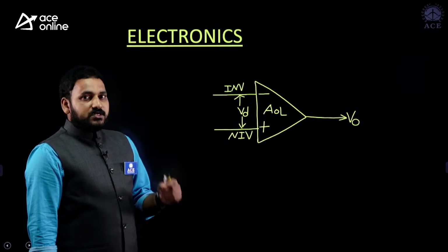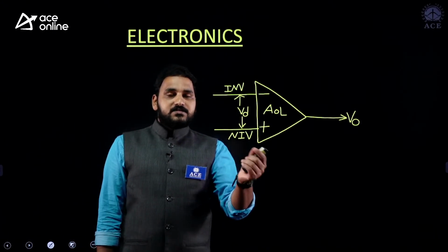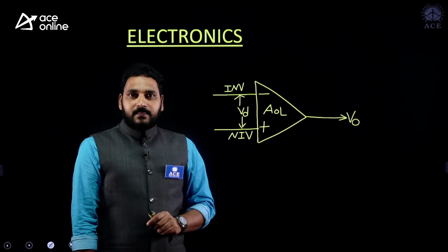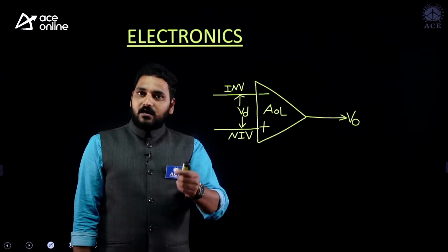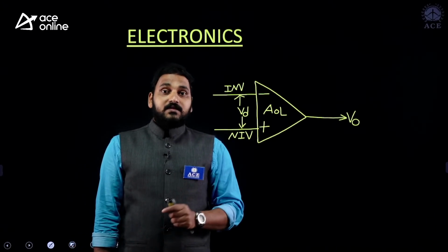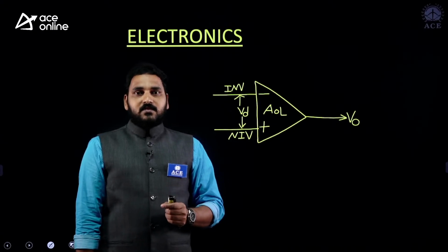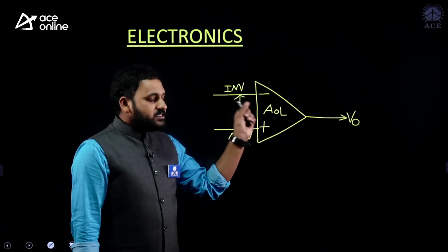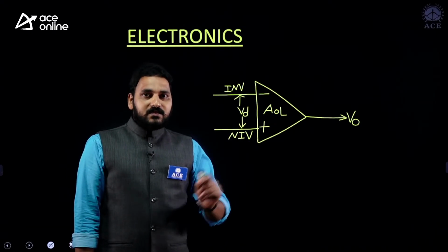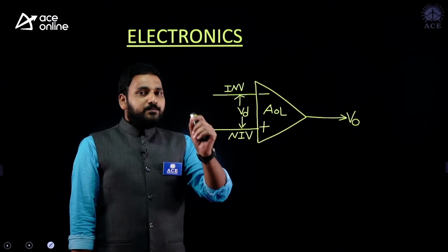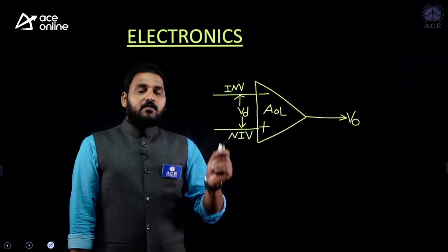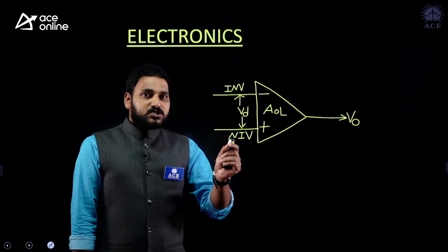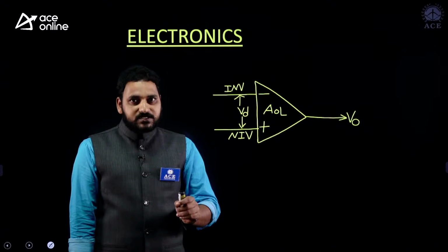We need to discuss the differential amplifier, balanced input balanced output type, next level balanced input and unbalanced output type, next current mirrors, NPN type and PNP type, and how they provide biasing for the transistors internally in the op-amp, the importance of the DC level shifter in the op-amp, and the last stage, that is the buffer stage or power amplifier stage.